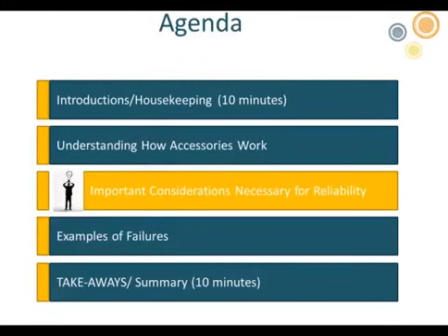In terms of birds pecking silicone rubber on terminations, I haven't heard of that one before, but that's an interesting question. I guess anything that nicks or causes damage to a rubber that's expanded and under mechanical stress, which cold shrink terminations typically are, and which are your silicone on the outside, anytime you nick that, it can cause it to split or cause problems because it's under mechanical tension from being stretched.